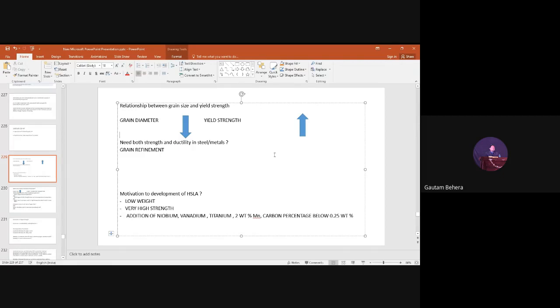They are strong carbide and nitride formers. Sir, they will not become soluble. They will form bigger spheroid particles at that temperature. Sir, grain coarsening will not occur.